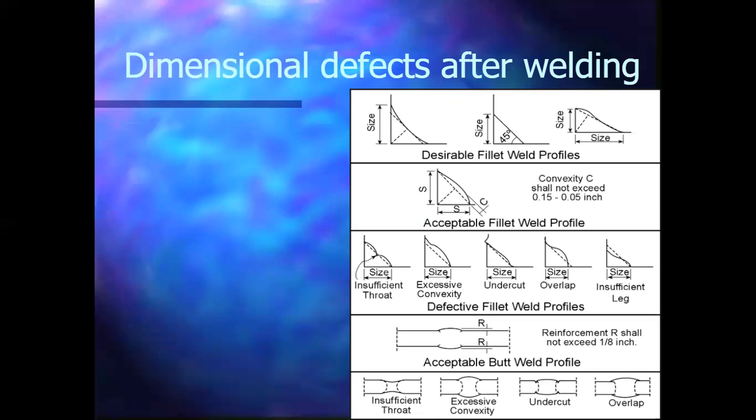This concave profile is going to help with stresses. Stresses are going to flow a lot nicer and easier here. With this one, where we have a perfectly flat weld, we have a hard turn here in the corner, or a hard turn here on the corner where the 45-degree side is. If we're drawing stress lines from the top of this weld down through the weld and out here, there would be a couple of corners on the road.